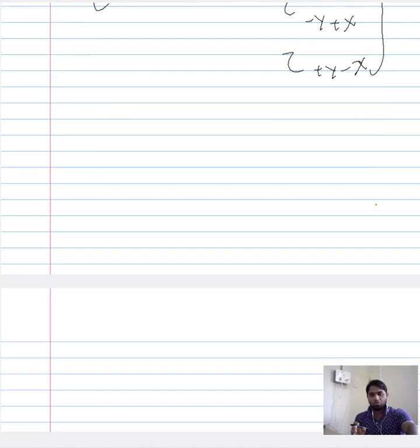Now what we have seen so far is that for an element, for a point, when you talk about a fixed point, then in order to maintain the rotational stability of the point, tau xy should be equal to tau yx. And for the sake of this argument, we just confine ourselves to positive shear stresses. And of course, we need to again understand that we are talking about a single point, and we have not defined or quantified the stresses acting on each. We have not quantified the components of each of the stresses.